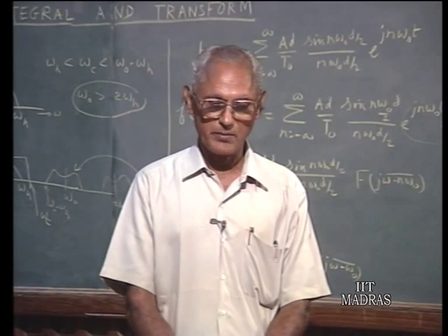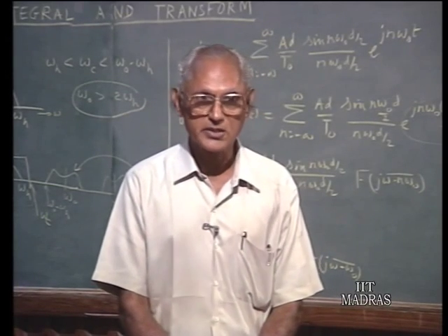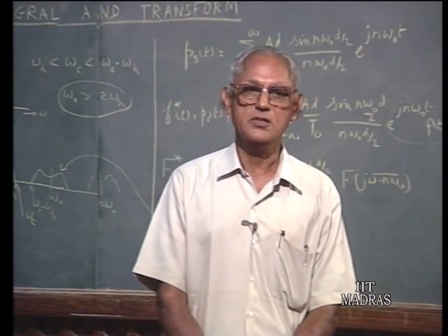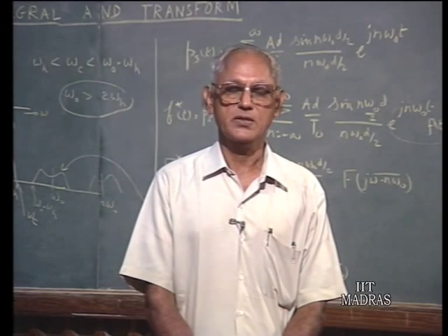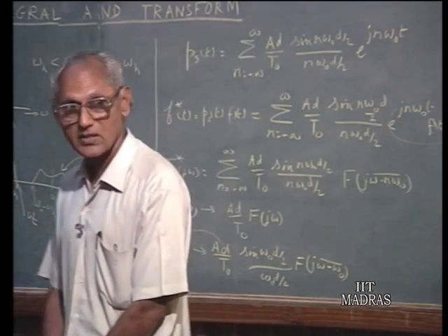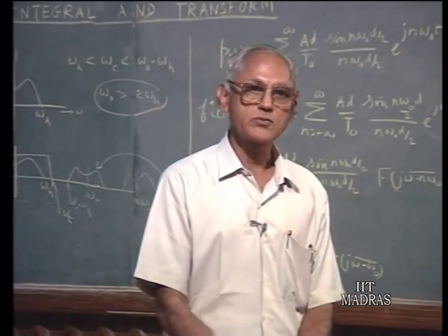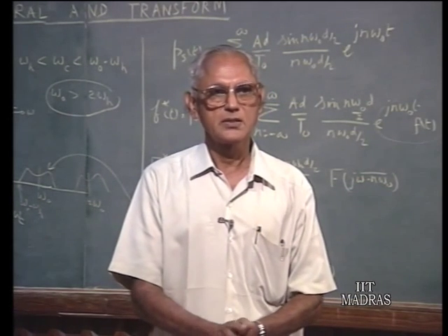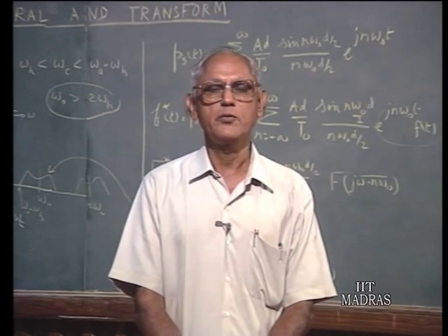The Laplace transform method offers greater convenience for the analytical solution of the transients in networks and systems, mainly because it enlarges the class of time functions which can be handled. That means certain types of functions like e to the power of 2t, for example, cannot be handled by the Fourier transform method, but the Laplace transform method can handle this. Secondly, the several delta functions which you may get in the Fourier transforms are avoided when you use the Laplace transform method. Because of these reasons, the Laplace transform method is a more convenient tool for analytical evaluation of the transients in linear systems.